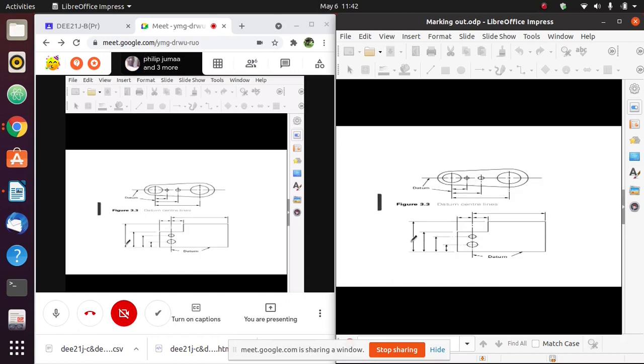Remember, when you do your engineering drawing, there are times that you make measurements from this center edge. The distance from this point to this point. Let's say this is a crank shaft or an arm. When I take the dimensions from this point to this point, then I've used those two center lines as my datum. So depending on the shape of your workpiece, we can identify different reference points. It can be an edge, it can be a center line, or it can be a point.